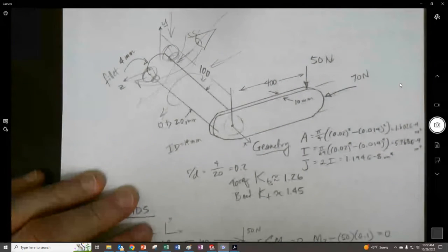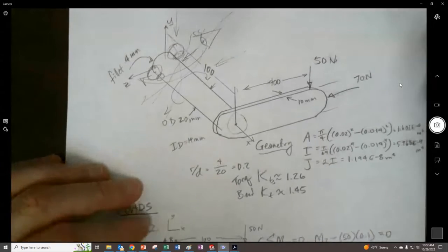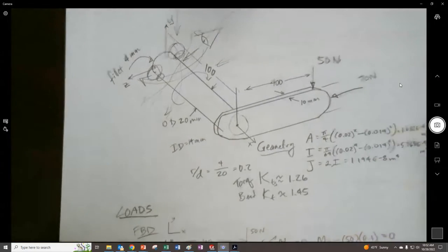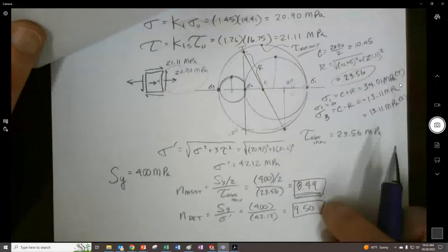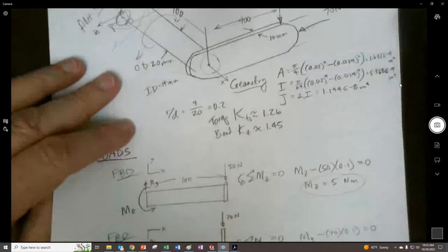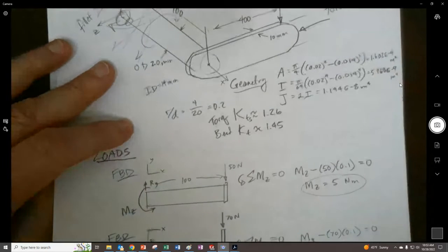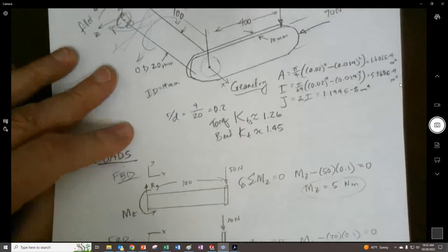So when doing an investigation on this, you probably want to try to find out what's the worst thing that can happen. And then overall, instead of thinking of the safety factor as being for a particular location, you can think of the overall safety factor against failure. Think of how the thing can fail, and then the lowest number for any failure that's possible would be the safety factor globally that you might assign to the thing to report how safe from failure the piece is.